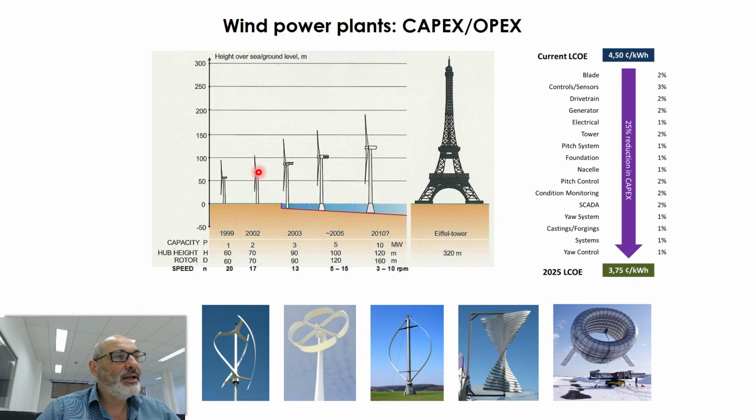You cannot exceed more than, let's say, 100 meters onshore, basically because it's very hard to transport your blade from the factory to the installation place. So that is related to the geometry of roads and lanes and streets. That's one of the reasons why wind farms are moving offshore, because offshore you have several advantages. You can build bigger blades, bigger turbines, so more efficient turbines. Well, you just use a crane on a boat here to construct these windmills, so you don't have a big problem.